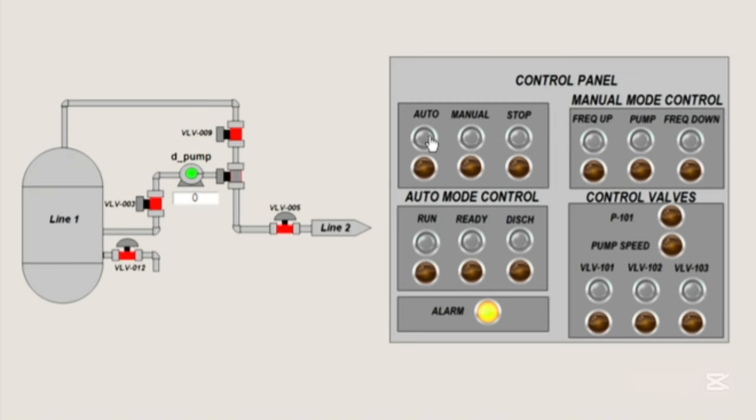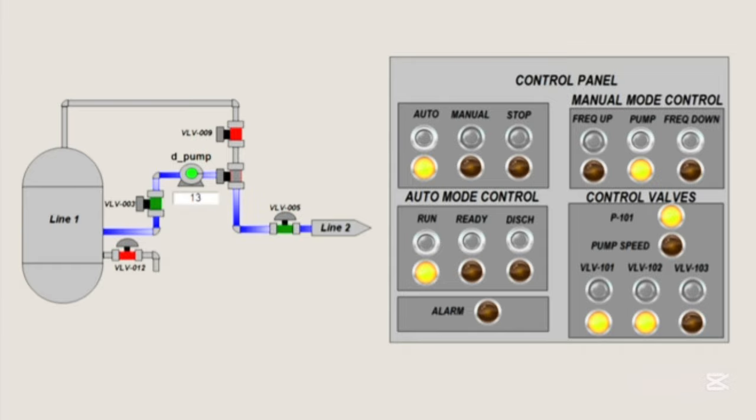In the software part for the M241, the visualization reflects the same logic that we demonstrated in the hardware section. Here you can see how the system responds to the pressure change, how pump 1 is enabled through valve 1, and how valve 2 opens only when the pump is running correctly and the pressure is in the safe range. The visualization clearly shows how the controller manages the process.